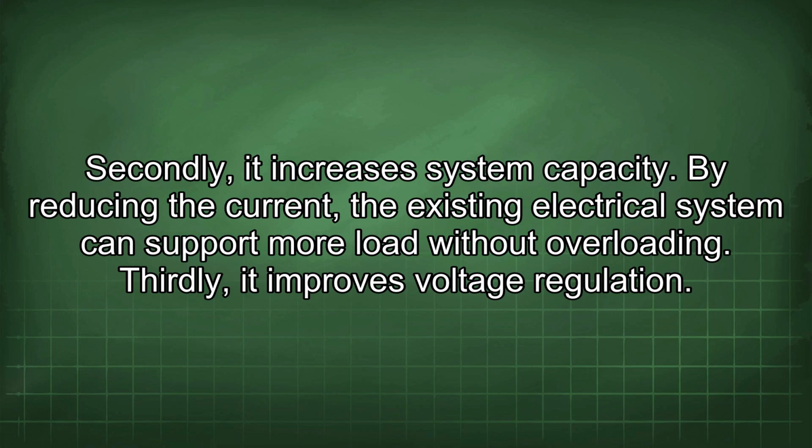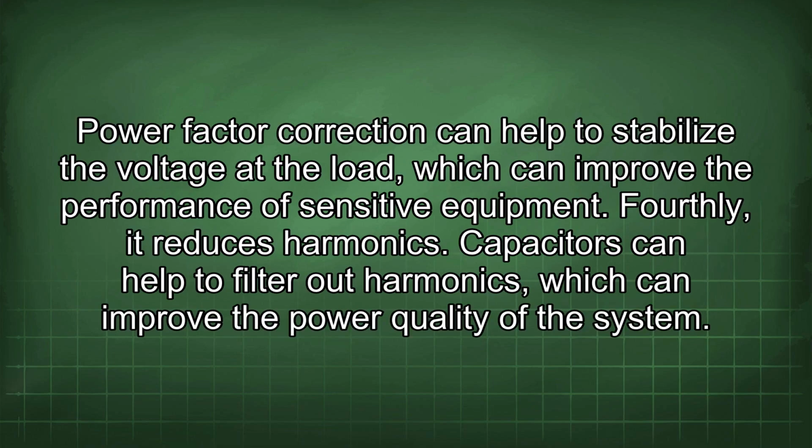Thirdly, it improves voltage regulation. Power factor correction can help to stabilize the voltage at the load, which can improve the performance of sensitive equipment. Fourthly, it reduces harmonics. Capacitors can help to filter out harmonics, which can improve the power quality of the system.